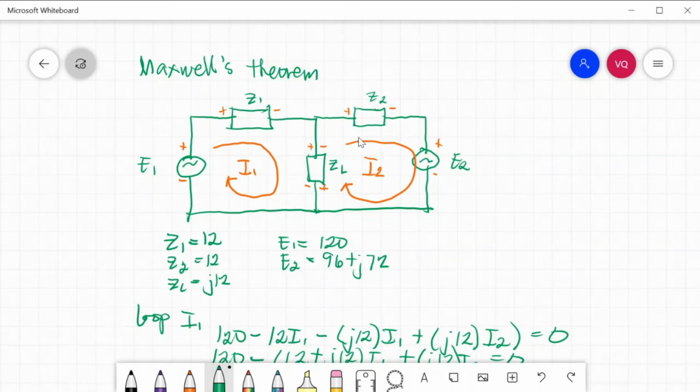example in Kirchhoff's. So this one, we have a positive and negative source here. Our impedance has a positive here and negative, because our current enters into this side. So this is a positive. And also at this side, the loop current I1 enters here, so this is a positive sign. And I2 enters here, so this is a positive. The polarity here will be positive also because I2 enters here.